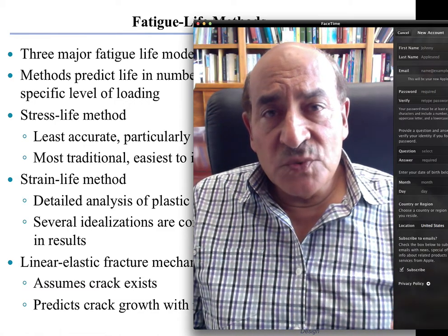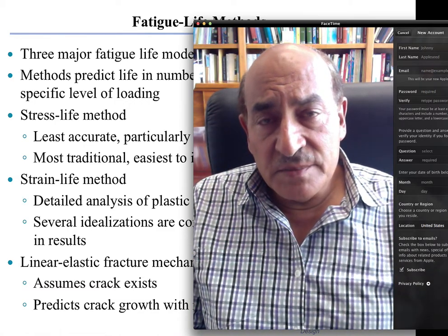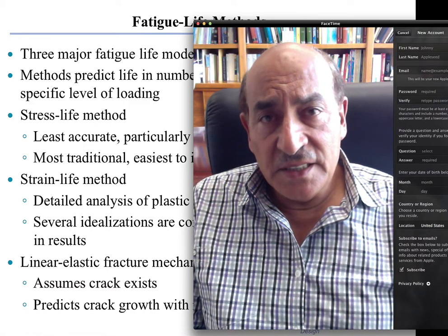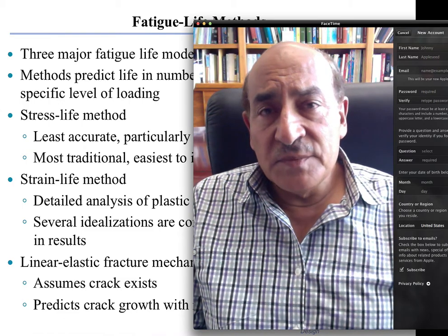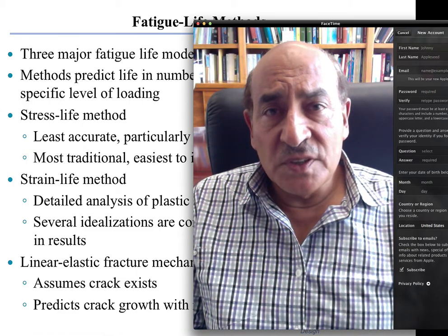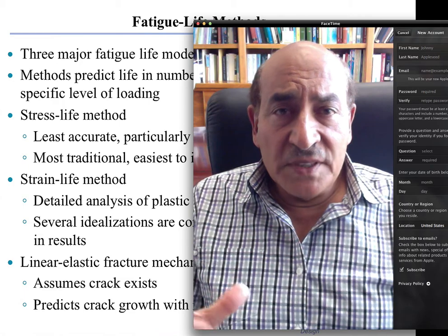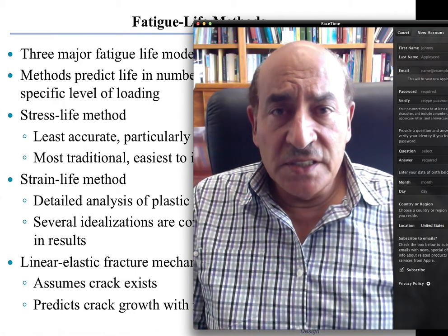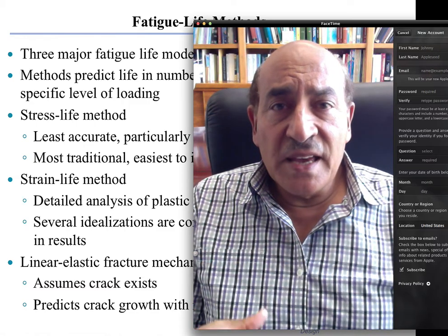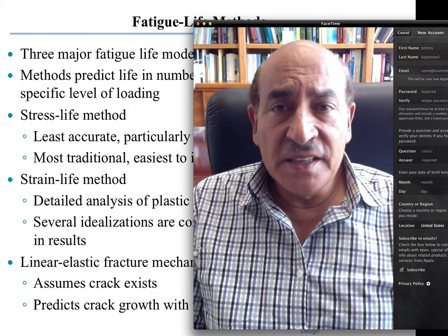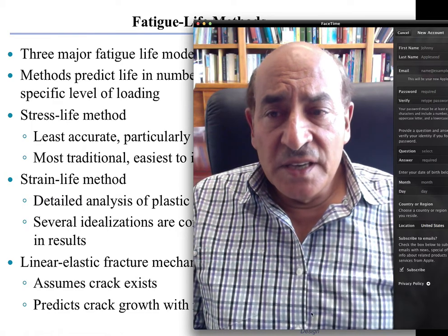And the limit is one of two things: either a plasticity driven yield limit, or a limit based on fracture mechanics, as we've learned before. So that's what I described here, the linear elastic fracture mechanics approach to understanding lifetime of components.